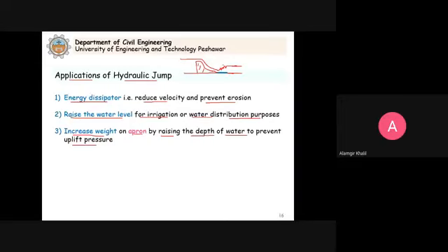And as a result of hydraulic jump, the energy is dissipated, but there will be turbulence in the hydraulic jump also. So we have to provide protection against that also. So on the downstream side of the spillway, this apron is provided here. This is known as apron. I will show you the pictures. This is known as the apron. And in here, because you study geotechnical engineering, there will be pore water pressure. So there will be an uplift pressure acting against it. There will be uplift pressure. This you will study in detail in irrigation engineering.